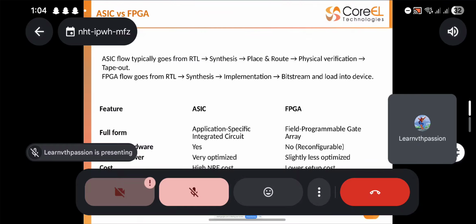So there are various foundries available, like Intel foundry, Samsung foundry. They will have certain rules for each foundry. If it passes the certain rules, then only they will take whatever GDSII you generated and form a tape out. Or else they will verify, and only if it is satisfied will they do the fabrication part. So under the verification, we have three different things. One is design rule check, DRC. Second comes layout versus schematic. Third comes parasitic extraction.